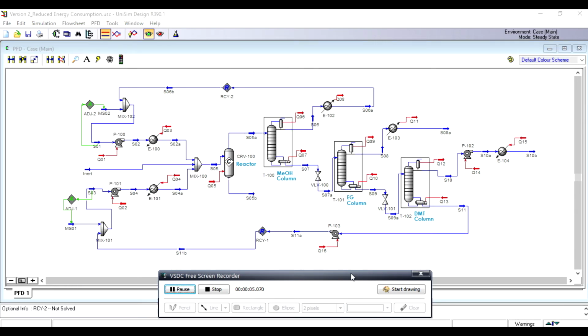This is version 2 of our simulation. The difference between version 2 and version 1 is that the feed inlets of methanol and PET increase in temperature and pressure individually before being mixed in the mixer. From the reactor onwards, the process condition is the same as version 1.